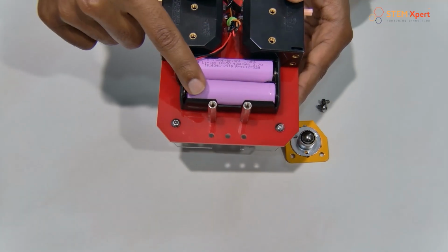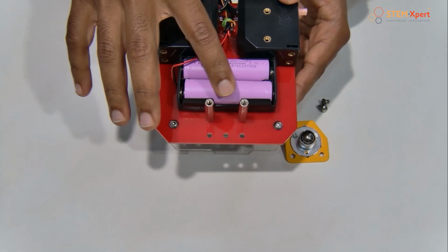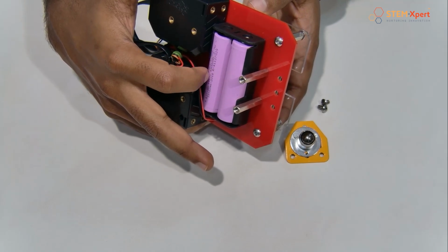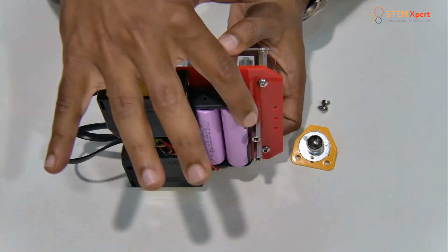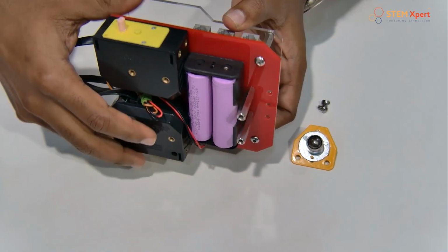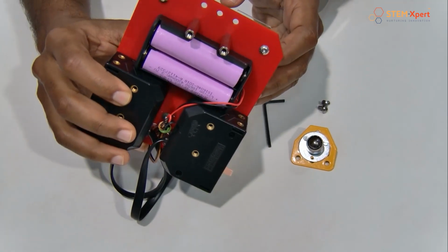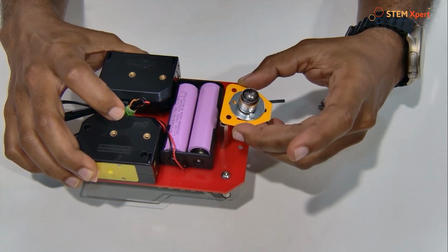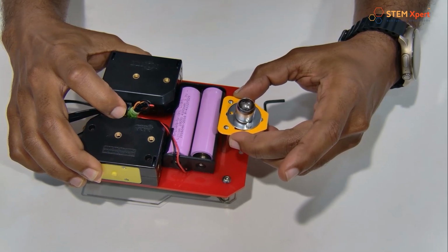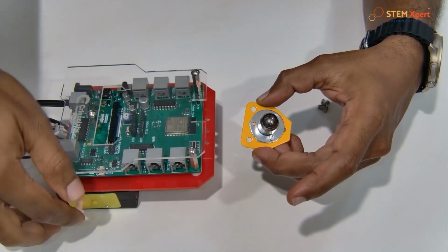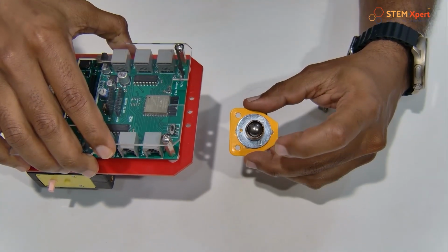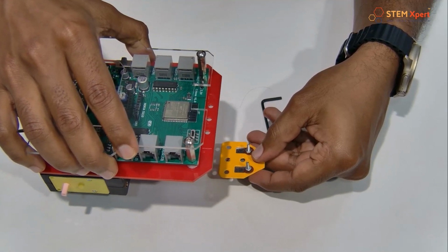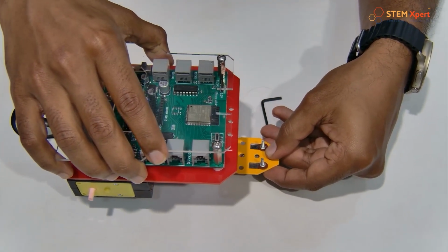On the bottom side of this robot, you can see two metal spacers. See here. This is the battery holder for powering up the board, and here this is the metal spacer. So what you can do is connect the caster wheel with these metal spacers like this. This is how you need to connect it. So this will be the front part. This rolling section should be going on the bottom side, and it will be like this. So then it will move. That's how we are going to make it.